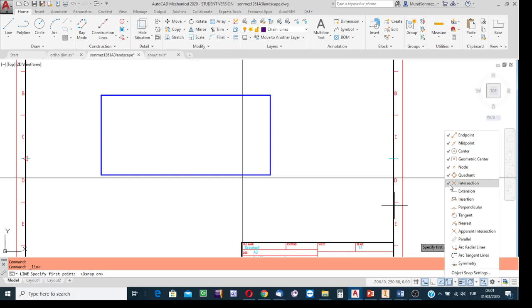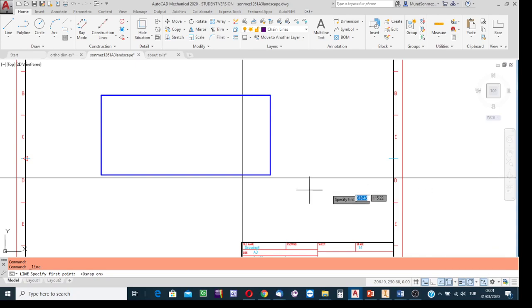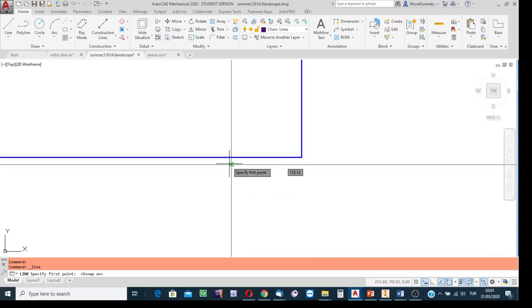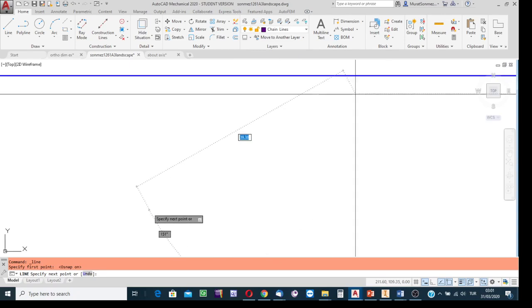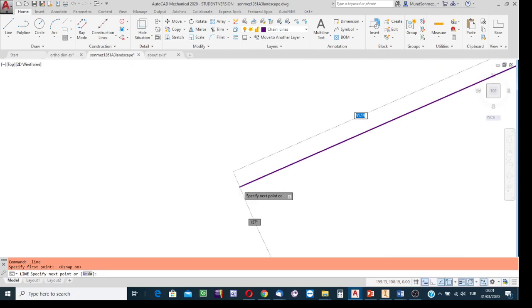If not, with a click next to this word, which is the name of the characteristic points, intersection points, enable the software for indicating intersections. The starting point for the chain line is an intersection point. It is the point marked by the intersecting transfer lines. Just indicate it using the snap facility and then move the cursor away.